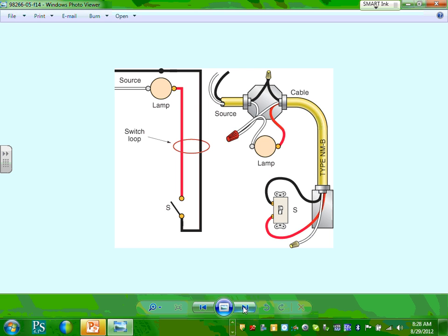Where's your neutral here? Here's a couple of wiring, guys. Now this is with cables. This is the new change, Jeff. Do you see that now? Now you have to bring your neutral right here if you're doing it with cable. Your neutral has to come and terminate. Can you see that? That's based on 2011. Brand new for you. You have to bring a neutral to every switch.